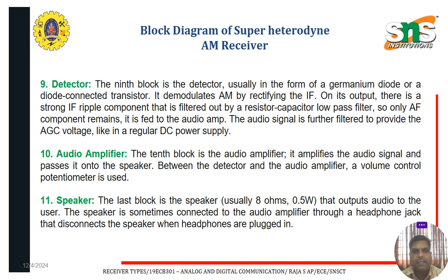The last block is the speaker. Usually it consists of an 8 ohm 0.5 watt speaker that outputs the audio to the user. The speaker is sometimes connected to the audio amplifier through a headphone jack that disconnects the speaker when headphones are plugged in.